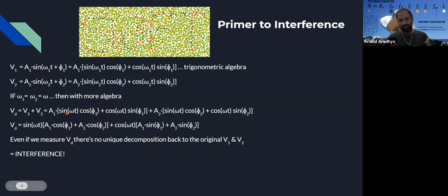When we want to make out what signal was actually delivered and at what frequency, we do this thing called a Fourier transform, and then you look at the amplitudes of the various components. That tells you which frequency had what information content and so on. It's essentially looking at the spectrum. That tells you the information that you need, whether it's encoded or natural information. You need to be able to do this decomposition in order to extract information.